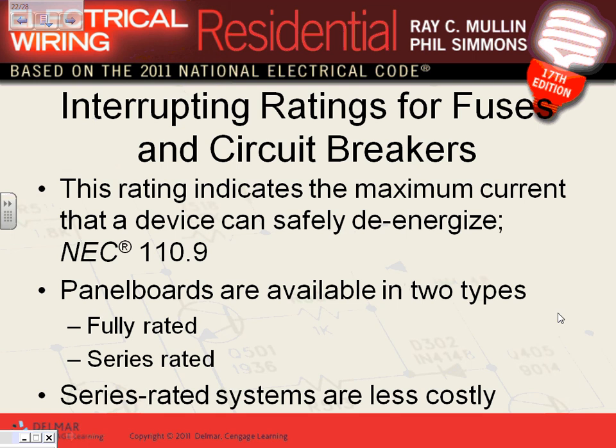Quick overview of circuit breakers. Any question? The code actually says if you have a fuse and the fuse interrupting rating is more than 10,000 amp, you have to label it. If it's 10,000 or less, you don't have to label it. More than 10,000, you have to label it. If it's a circuit breaker, if it's 5,000 or less, you don't have to label it. If it's more than 10,000, you have to label it.